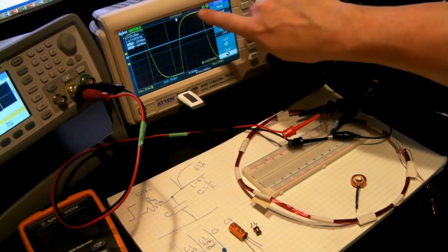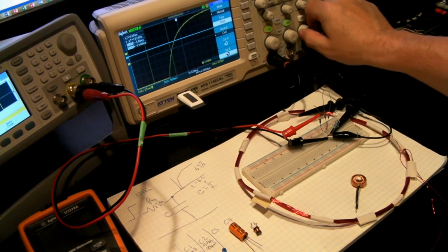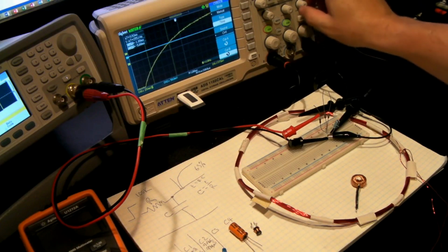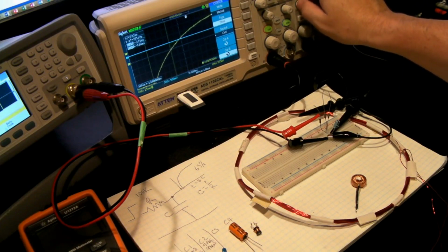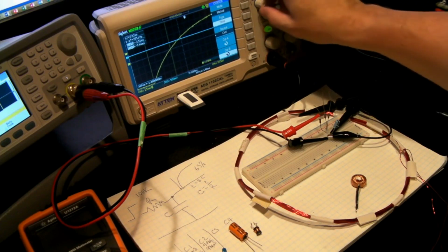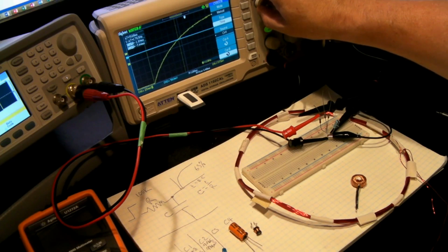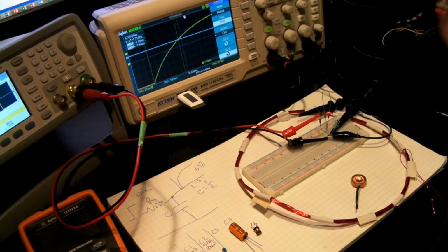We've still got this characteristic curve of an RC network, so I'm going to increase my time base out again so that I can do some measuring here. Adjust this onto the first cursor, just being lazy rather than move both cursors, and move this second one to the intersection of the 63% mark, which now is reading 5.5 milliseconds.